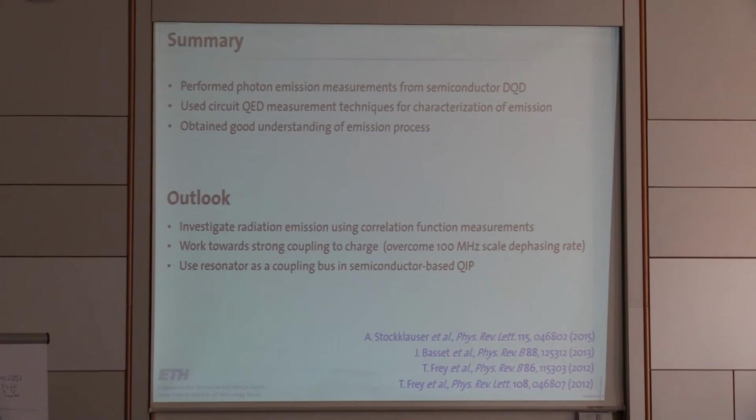So gallium arsenide is piezoelectric, and also with Peter, well, maybe he knows more about it now, we tried to estimate a bit what one would think the cavity Qs should be on a piezoelectric material for these waveguide structures. And maybe Peter knows more. The best Qs that we typically get on gallium arsenide are maybe 5 to 10,000. So maybe more like 5,000, and that's good enough for this.